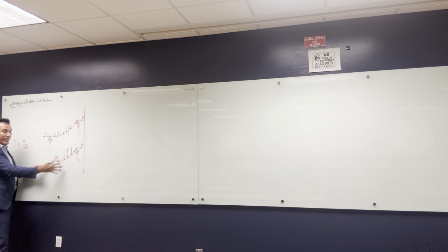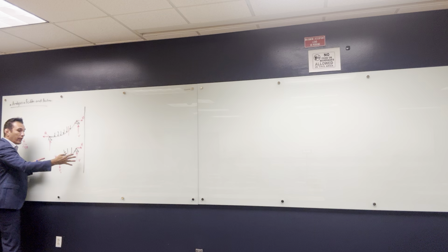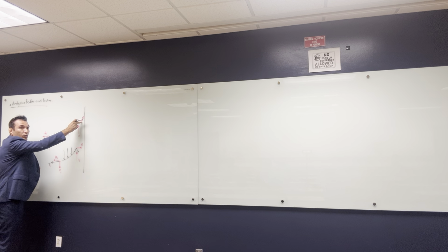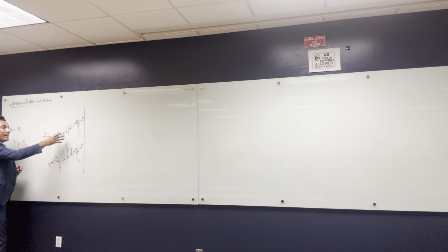So when I take this section out, when I do statics, make sure that this is stable. When I do the sum of the forces in the x direction, I will find that H, the horizontal reaction here, is equal to H1, because there are no other horizontal forces. If you cut in this section, you'll find that H1 is also equal to H4, H2, H3. So the horizontal force is always equal to the horizontal reaction, as long as the cable doesn't have any horizontal loads. All the loads are vertical. Okay, so I solved this one.